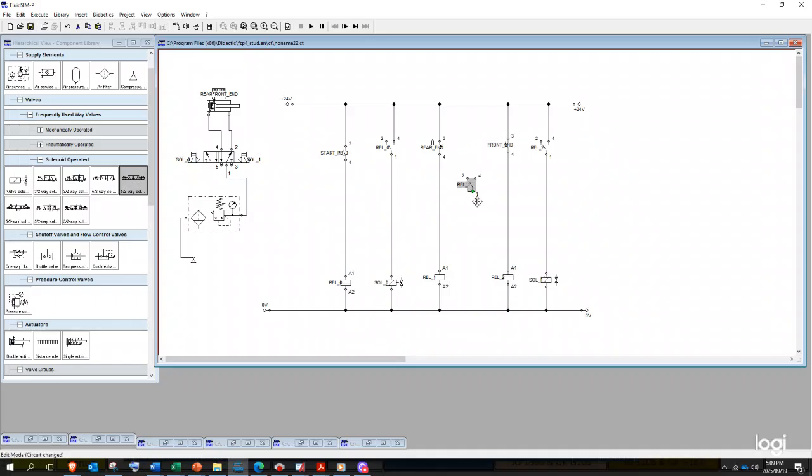So what do we do with this changeover switch? We can't have a third valve solenoid, because all the solenoid operated valves only have 2 points for our valve solenoid configuration. Because this limit switch is a condition for our piston rod to advance, and we use this push button to advance, we connect these two in series.